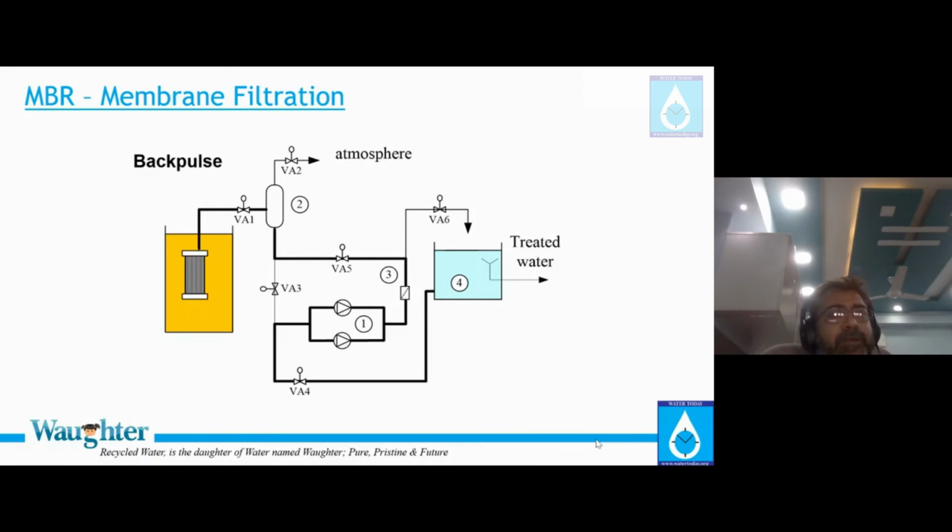Because filtration has been stopped. So that is one phenomenon. The second thing is that the level is increasing as well as you are putting additional water into the MBR tank, because some treated water is coming back. So again, the levels are changing. So there is an important role of all this kind of hydraulic understanding in MBR designs.